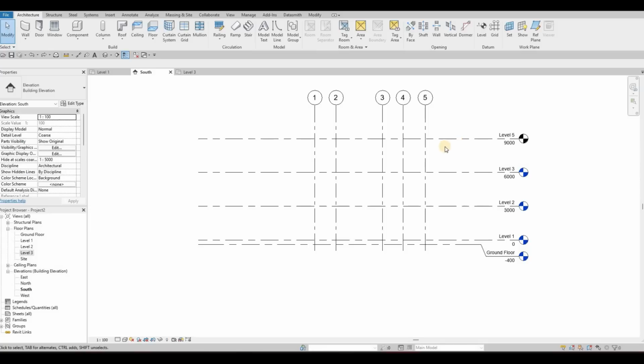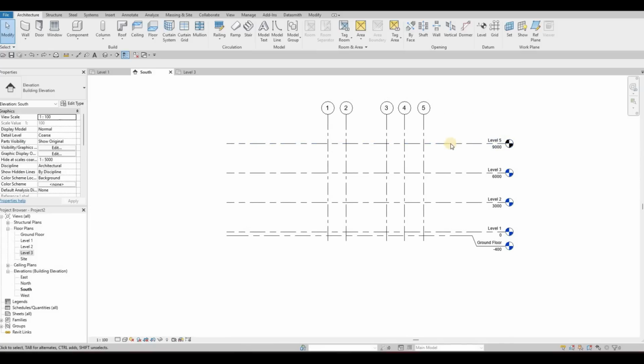If that happens, the way that you added the level in regards to just copying is different. So for me, when I added the ground floor and then the level 3, I use LL, and it will instantly add the level here.